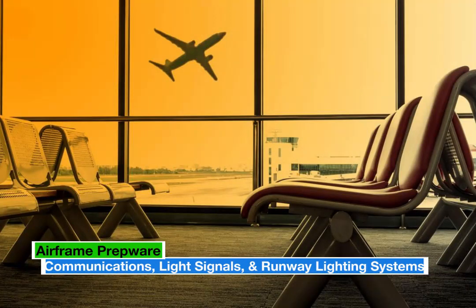How much clearance for the seat bottom is required when installing radio equipment under a seat? 1 inch with the seat occupied and subjected to maximum downward seat spring deflection. Which of the following is a two-way text communication link between an airliner in flight and the airline's main ground facilities? Aircraft Communication Addressing and Reporting System, ACARS.